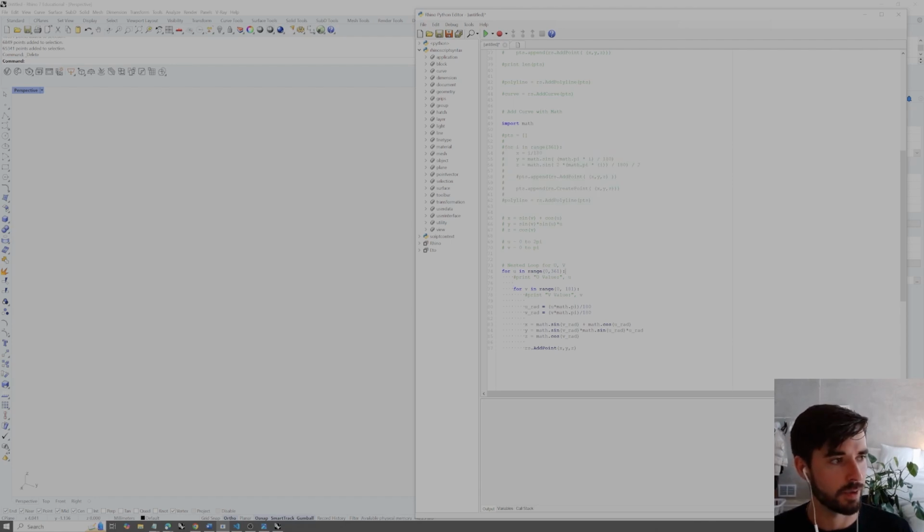One important note though is that we don't want our polylines to be made after all of the u and v values are iterated through, because this would just give us one continuous polyline looping through all of these rows. What's important for a surface to be constructed is that we have those rows separated in separate lists.